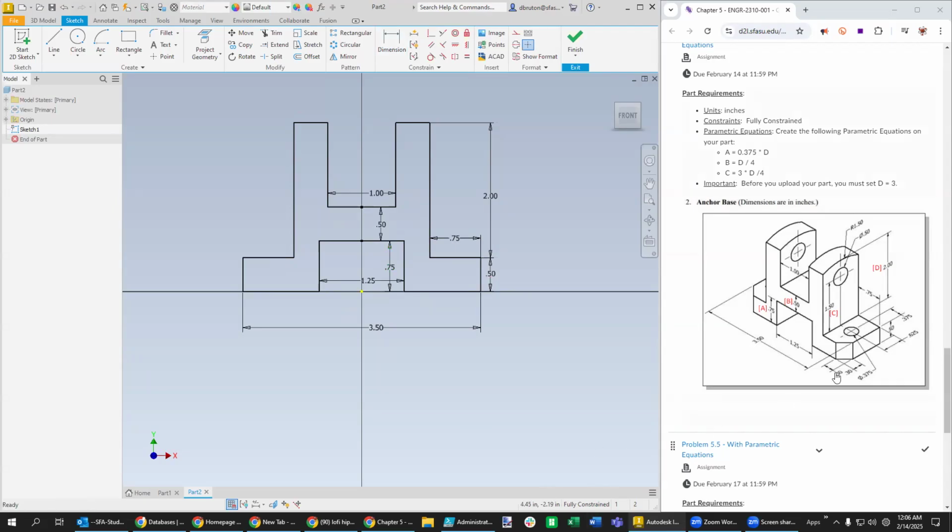What we can then do, before we start to extrude this, is to establish some of these connections if we can. So we see that they're all dependent upon D, which is the height right here. So let's look at part A over here. And the height of D is that 2 units. So it's called D6. And so we want A over here, which is going to be this one. We can move it over.